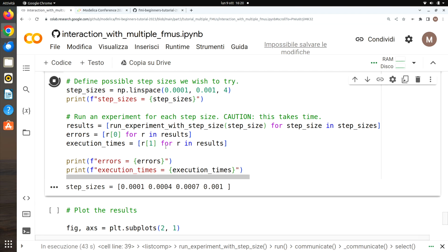Meanwhile, does the tool define the consistent initial conditions? This tool, yes. It exchanges data in the initial part, but if you mean really reaching convergence, then it only does so with a command line option, using stabilization, but I wouldn't swear by it. I think tools like Dymola do a much better job at getting this initial problem.